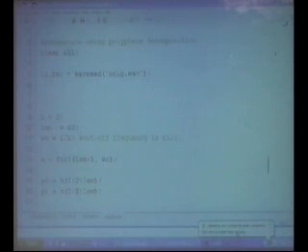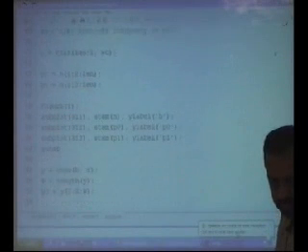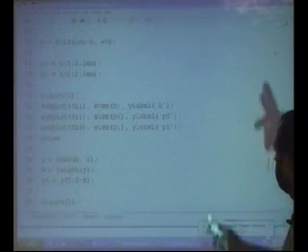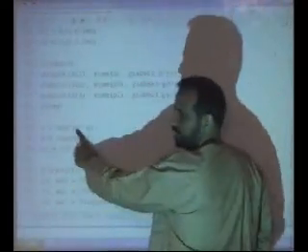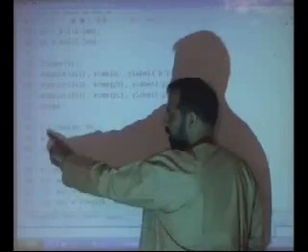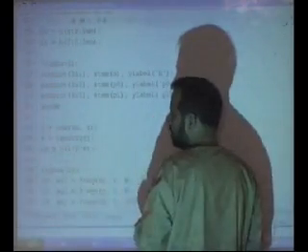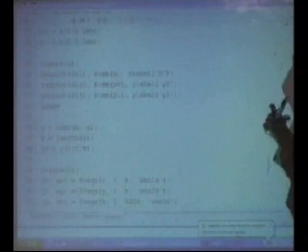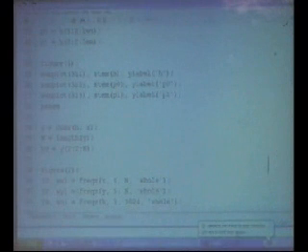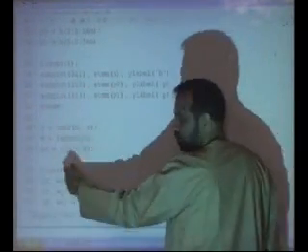Okay, now there are two ways, even in MATLAB. Here I am plotting H, P0, P1. One is you convolve X with H, which means you get the output and then you throw away samples. Here I am throwing away the first sample and keeping the second one, just to show you the equivalency of the two. This is one way, but you are doing a lot more computation. Even MATLAB is doing a lot more computation, because you compute and then you throw away samples.